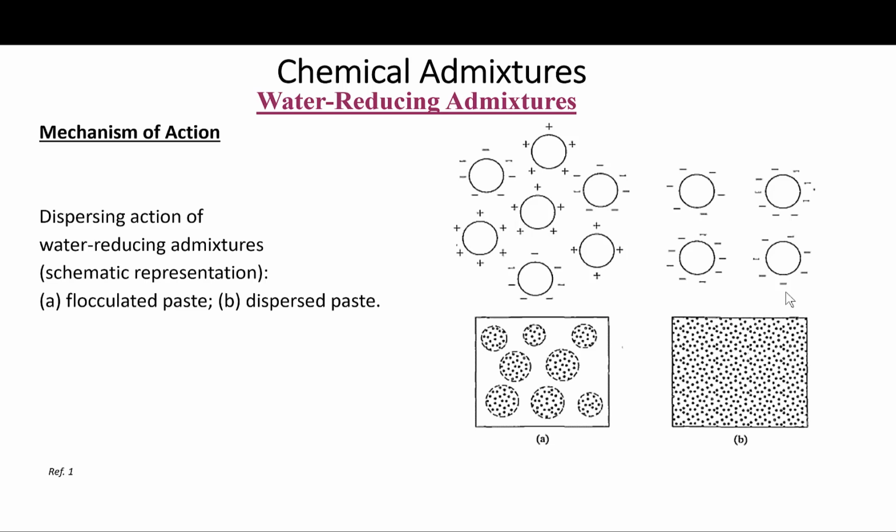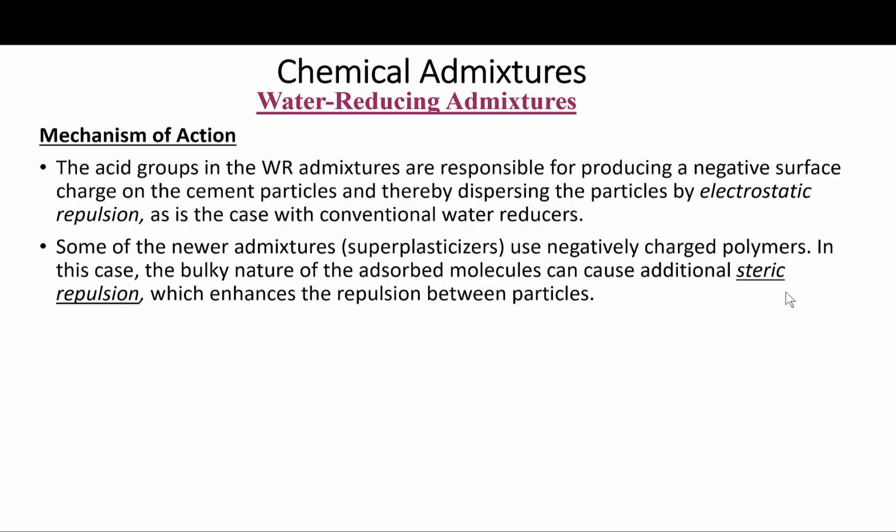tendency for flocculation is common to all finely divided solids. For example, deflocculating agents or plasticizers are commonly used with clay water systems to produce free flowing slurries at low water contents. Okay. The use in concrete technology basically is analogous to that use in the case of the clays, and in some cases it also involves the same chemicals.